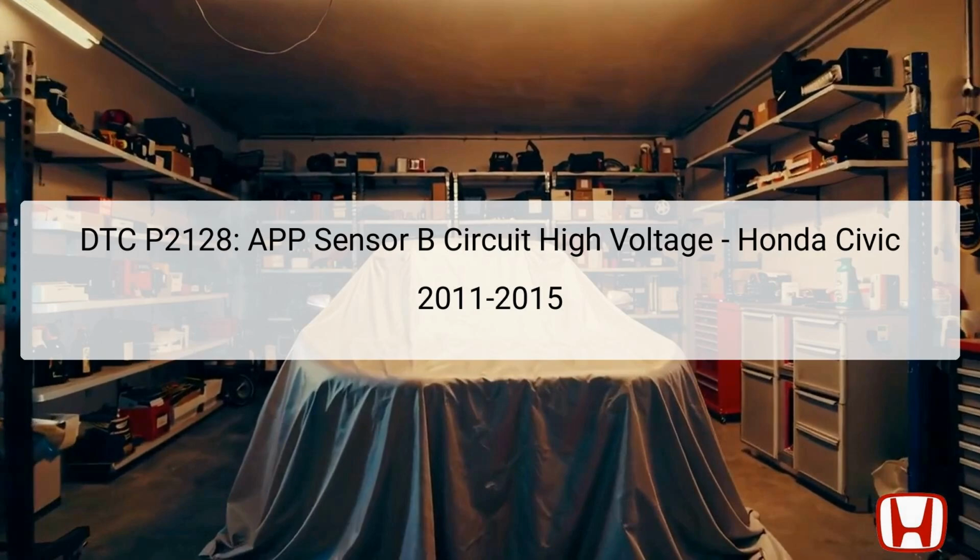The Diagnostic Trouble Code, DTC P2128, refers to a high voltage reading in the APP sensor B, often known as the throttle position TP sensor E. This issue is primarily linked to the accelerator pedal position APP sensor, which plays a crucial role in vehicle performance. It detects the position of the accelerator pedal and sends this information to the Engine Control Module, ECM, to adjust engine power and optimize fuel efficiency.